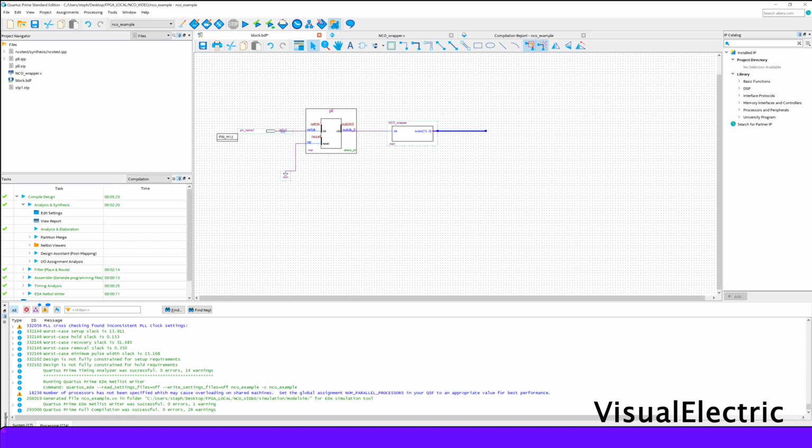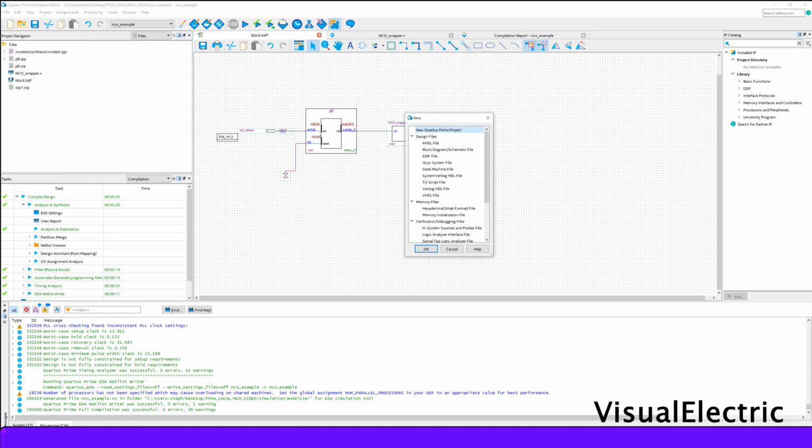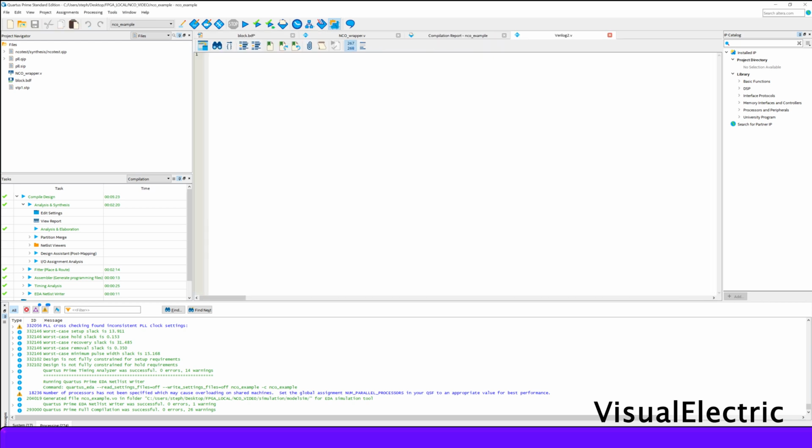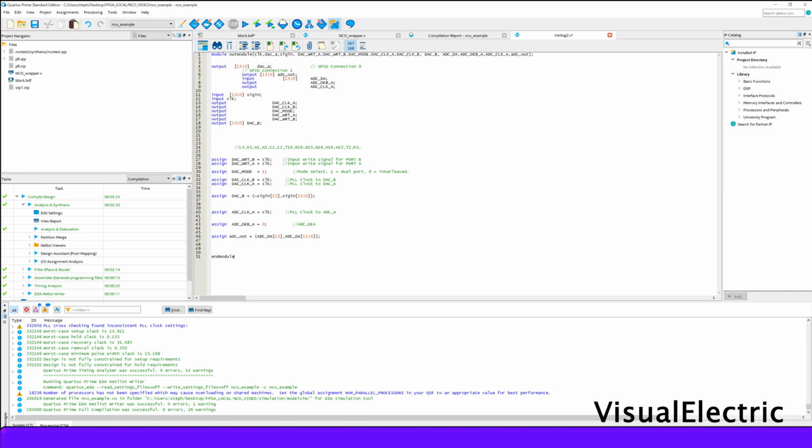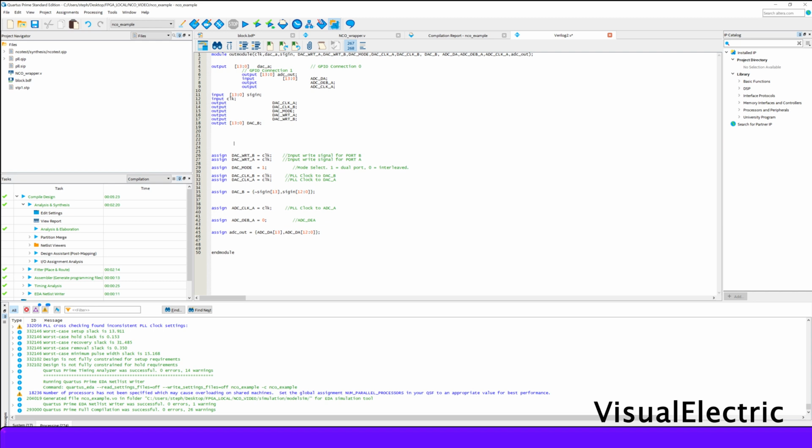So what I'm going to do now is write some interface code for this 14-bit DAC. In fact, just to save time again, I'm going to copy and paste some existing code from another project. This one is interface code for both the 14-bit DAC and the 14-bit A to D converter. I'm not sure if we're going to use the A to D converter in this video, but certainly we will be using the DAC. You can see here I'm targeting channel B because this is a dual channel digital to analog converter. It has channel A and channel B.